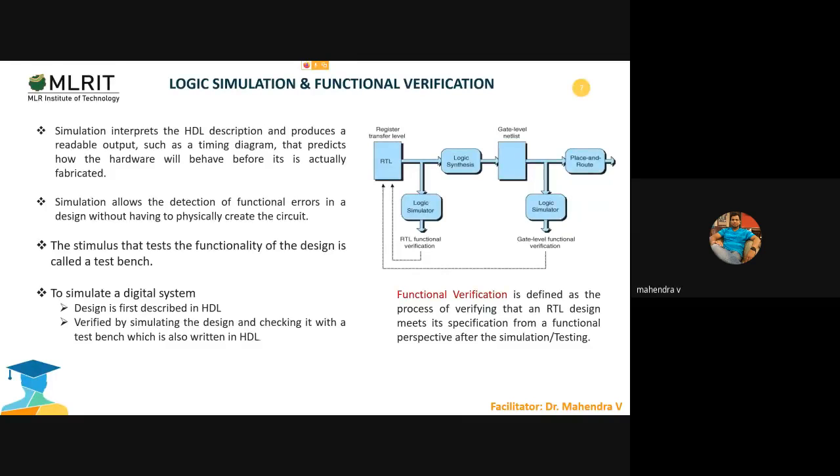The simulation results may not give you a pass in functional verification. Functional verification should pass only when your simulated results are matching with the expected results. That is what functional verification states: verification of simulated results with the expected results.